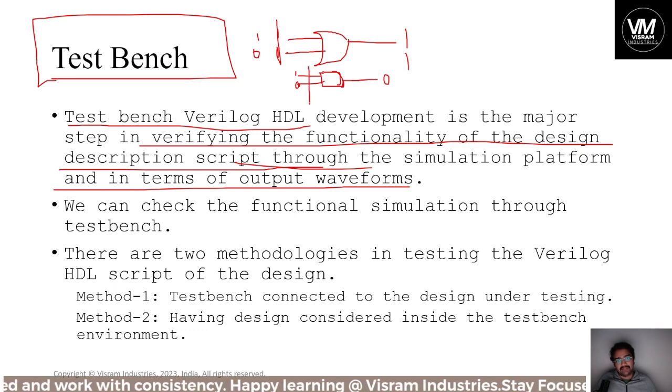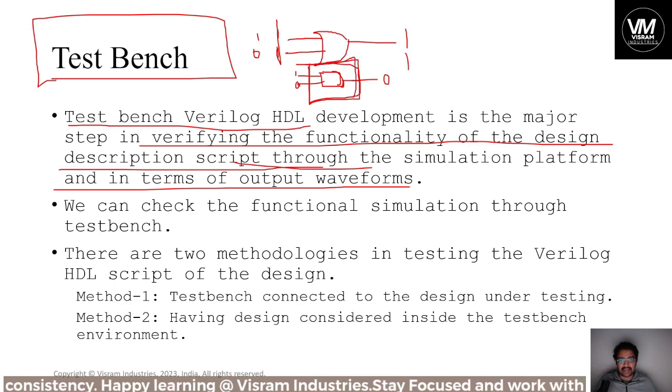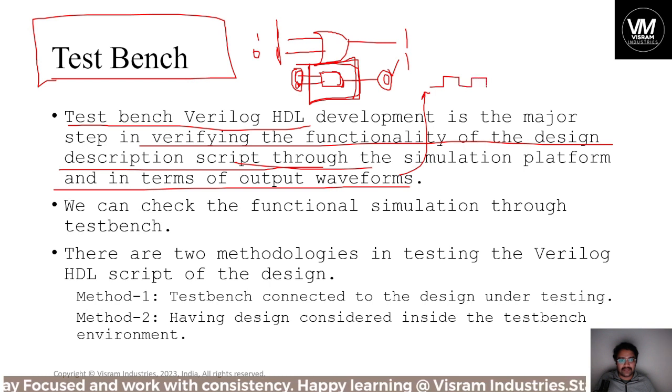What are we doing here? In the design Verilog HDL file, we are designing the logic circuits or the logic design, that entire architecture of the hardware. But in the test bench, we are assigning some values and verifying the output. Are we getting the same operations or same output at the given point of clock or reset? So that is called test bench. We will see the waveforms in this way. In the output, I'll show you some of the waveforms in the later stages.